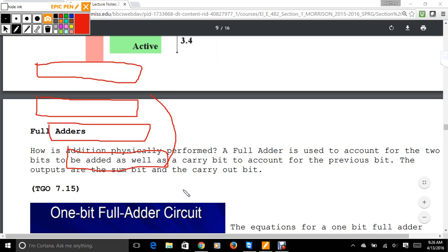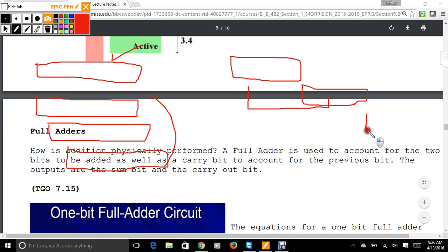So there's a compromise called multi-cycle, where if I only need 3 stages, I only do 3 of them. If I have load word, I need 4. So it'll cut down, it'll be less than single cycle, but it requires a little bit more overhead. So, branch equivalent order requires 3, store word requires all 5, and so on.